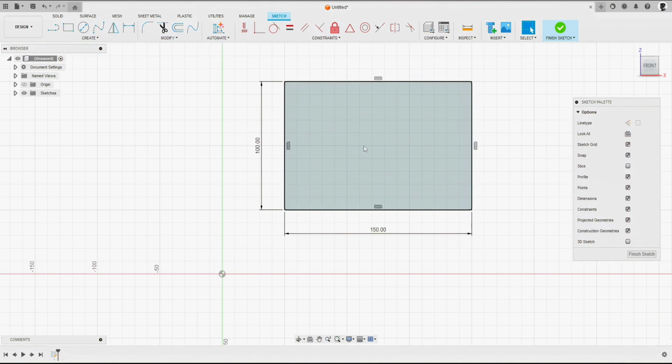So for the linear distance here, let's cover 40. And for the angle, we can control it with this wheel, or we've got the parameter box there. I want to input an angle, go for 20 degrees, press enter. There we see our parameters, our dimensions have appeared there. And again, we can adjust these. So change that to 30 and change that to, let's go for 15. So that is the distance and angle chamfer.